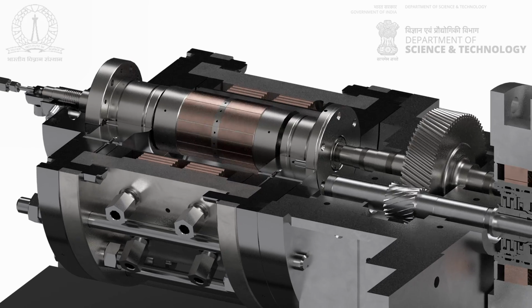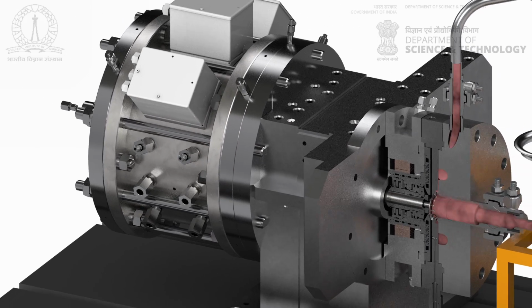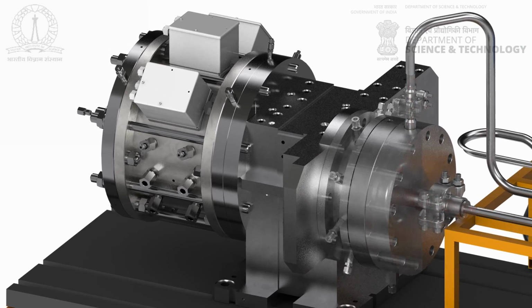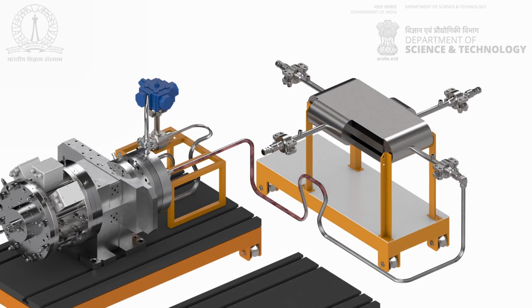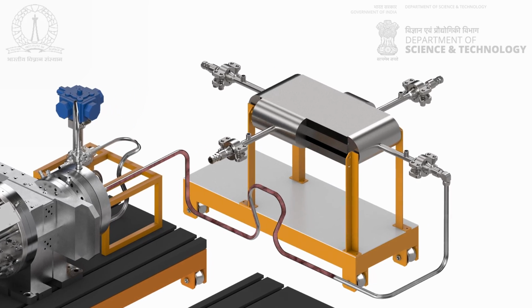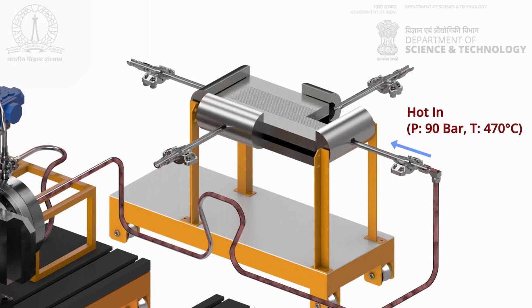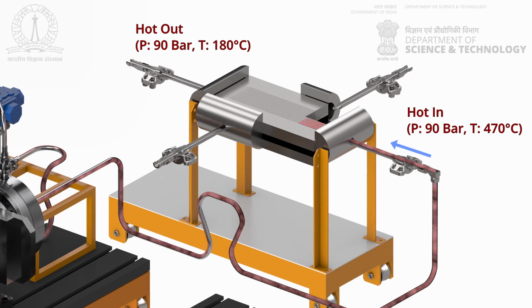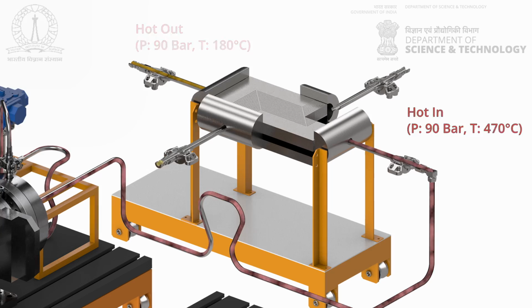The temperature drop across the turbine in an SCO2-based system is smaller than in conventional systems. The turbine exhaust is therefore at low pressure but at a fairly high temperature of about 470 degrees Celsius. Instead of rejecting the entirety of this high residual thermal energy to the ambient, some of it is recovered by passing it through the hot side of the recuperator to exchange heat with the low temperature CO2 from the compressor